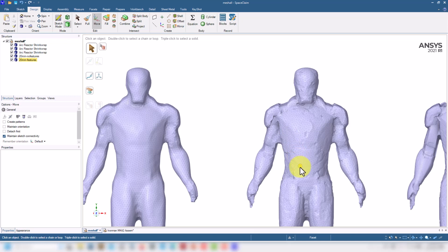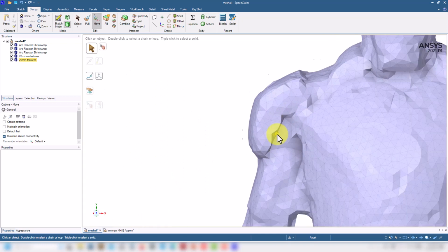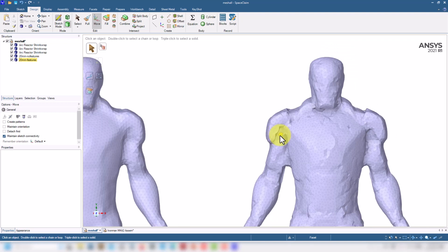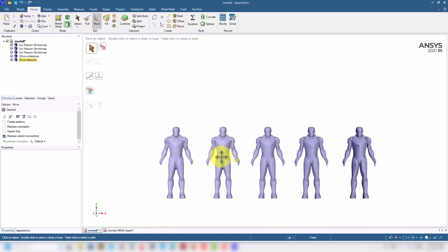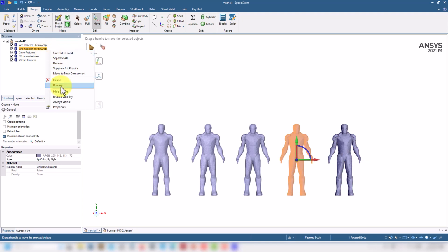But in doing so, it might add some other problems. You start to see that at those angles your mesh is probably going to have quality problems. So this is up to you. This is part of the assumptions that we're going to discuss later: what the problem is, what we need to do, and what we can neglect, or what hypotheses we can make. So this will be the 2 millimeters with features. Then we go to 5 millimeters.